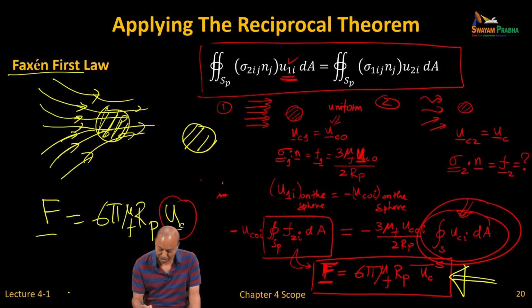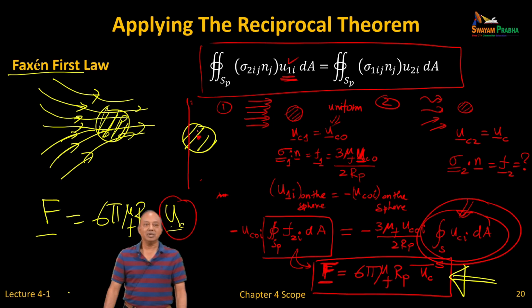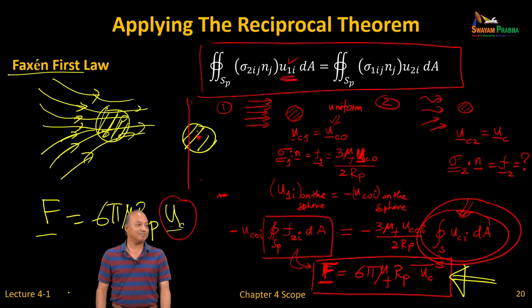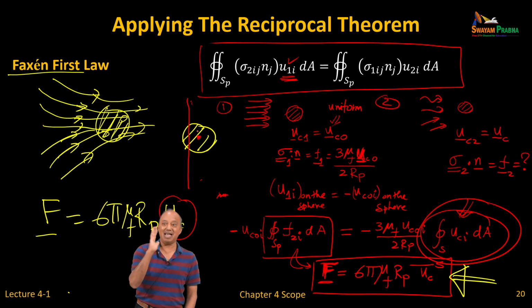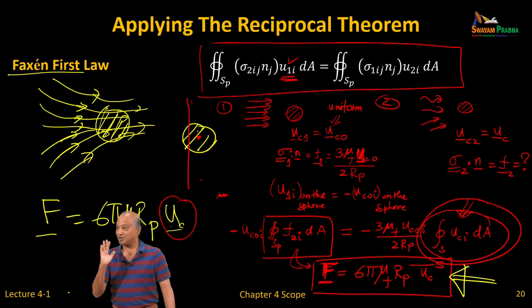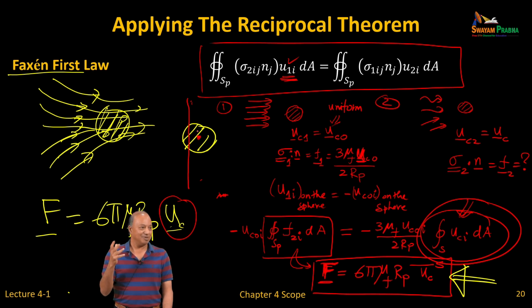For example, if the shock is out here and hasn't reached the center of the particle, you may think there is no force, because the fluid velocity at the center of the particle is still 0. But the front is being slammed with the flow and is already seeing tremendous force. So you just can't use the velocity at the center of the particle.